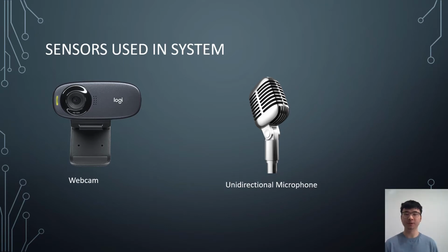The diaphragm has the freedom to move at the center and responds to the pressure created by sound. Behind the diaphragm will be a stationary metal plate to create a capacitor that is used to measure the distance between the two materials. The change in distance will cause a change in voltage, which is equivalent to the pressure of the sound wave. The microphone can sense this because the electret has a fixed charge, and any change will denote a sound wave. The output voltage from the microphone is small, so an amplification device will be required.